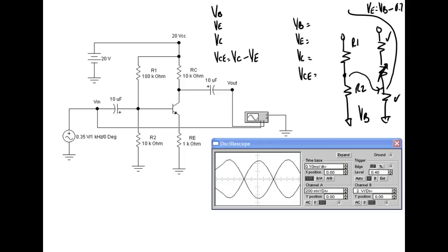So when I hook up my scope right here, this is my input coming in. When I move it over here, this is the same input, but now it's riding up on top of DC, right? So that's what the capacitor does. It lets the input come in, and I'm overdriving the transistor because we're on this original circuit. We're supposed to be setting at 2 volts, and if I put 2 volts in, then it's going to cut it off and saturate it. So we'll look at this later on and show you what's going on. But this is the output.